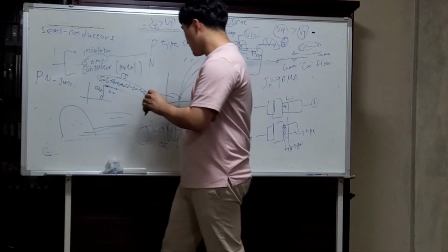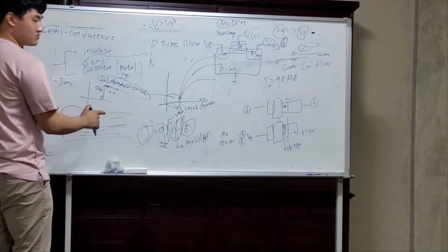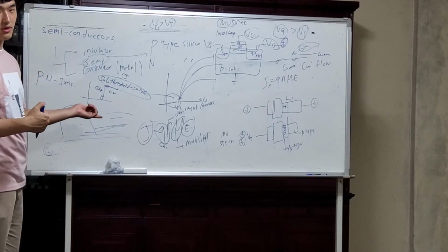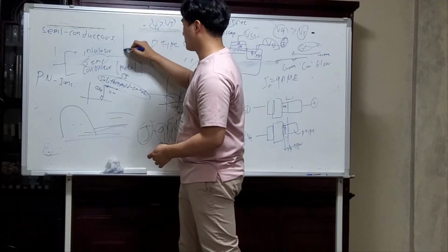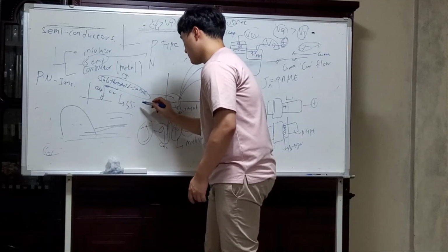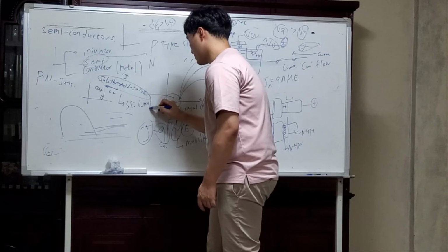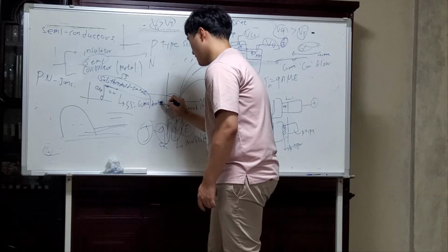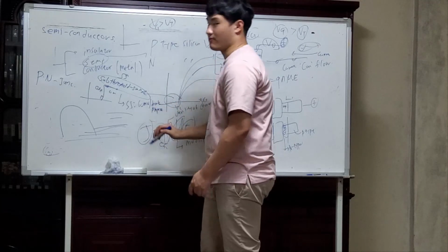Since the subthreshold swing is very small, we look at this factor on a logarithmic scale. The S can't be under 60 millivolts per decade of current, by Boltzmann's law.